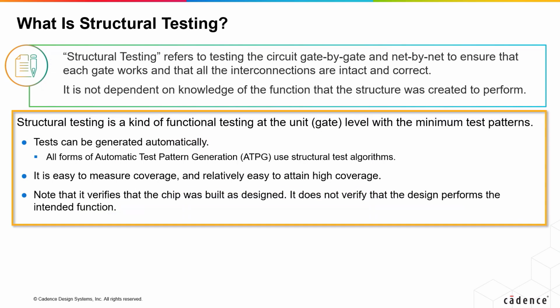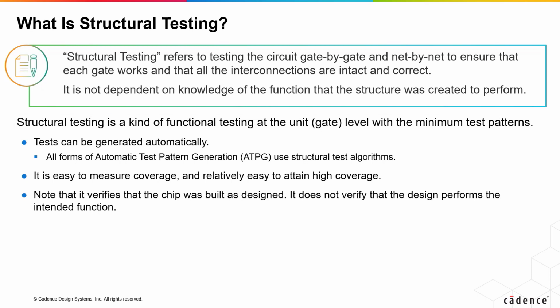In addition, the pattern generator only needs to understand the function of a small set of primitive logic functions, AND, OR, etc., not the function of the circuit as a whole. Thus, it can be automated. All modern test tools use structural testing for automatic test pattern generation, ATPG.